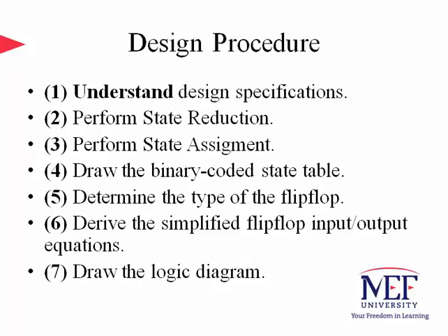Next, we reduce the number of states if we need to, using state reduction techniques. If we draw the state diagram wisely, most of the time we may simply skip this step because it will no longer be needed. But for complicated designs, this step can be a lifesaver. Thirdly, we assign binary values to the states of the system. We later obtain the state table where states are represented by binary codes.